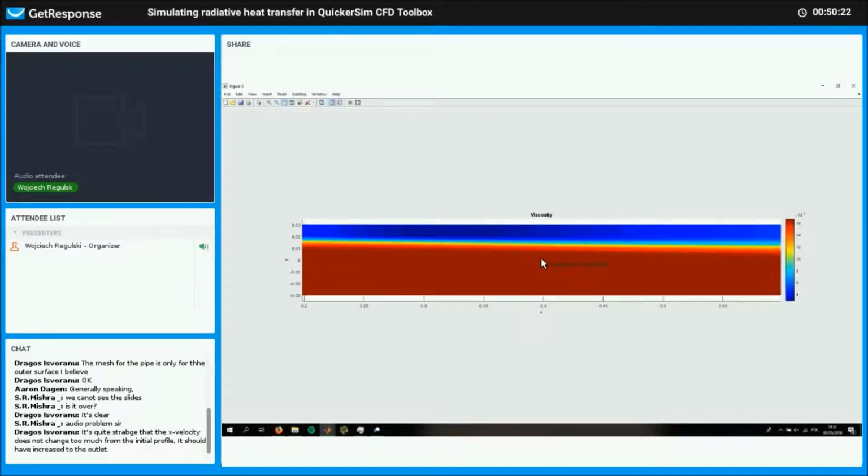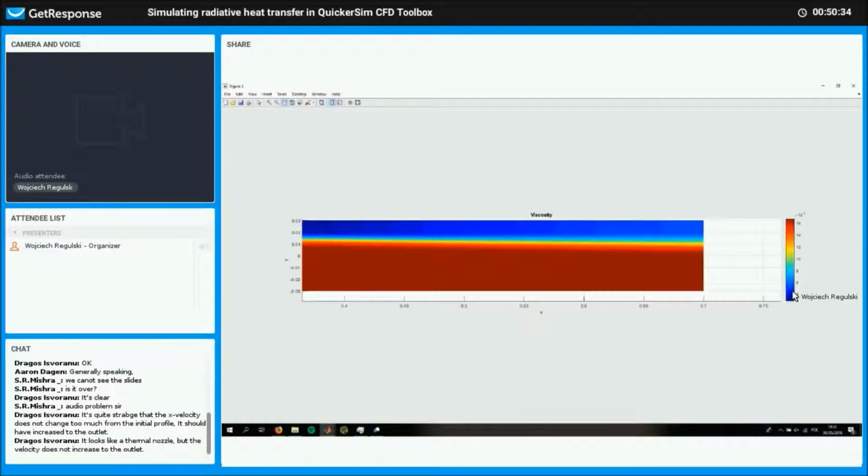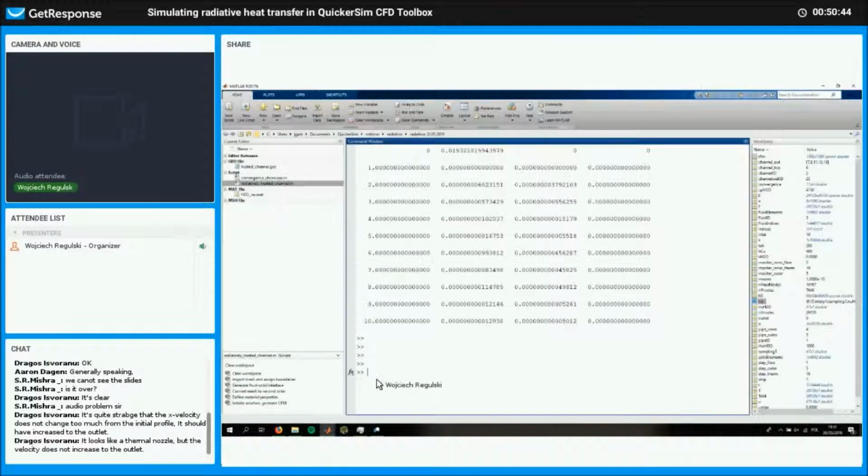1100 Kelvin. So the fluid would look as if it had constant temperature, because as you can see, the change is fairly small. And once again, the change in viscosity is from, I want to say, 3 to over 16. This is in meters squared per second because it's kinematic viscosity. All right, so this is fairly clear, I believe.